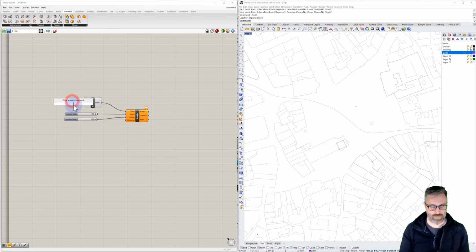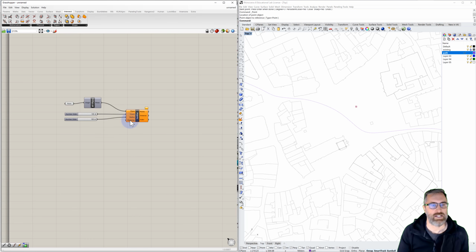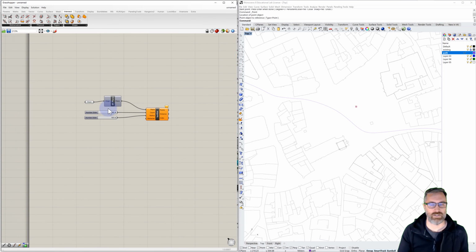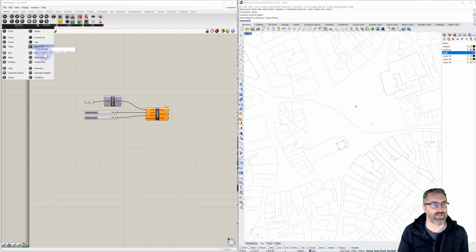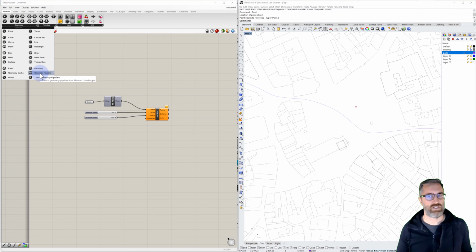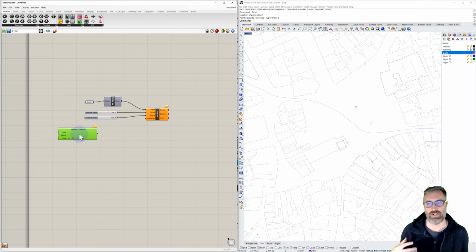And our origin, let's set a point for this. Plug in our point. We'll grab our point by setting one point, and we'll use this point in the space. Let's set the plane for us. We can hide that. And now we need obstacles. What I'm going to use for obstacles, this is a new tool. We're going to use a geometry pipeline. So under geometry, we can see Geometry Pipeline. What's really nice about this is that we just set a series of curves and lines onto a layer. And so we'll use Geometry Pipeline. And what it will do is it'll basically query something based on a layer or based on names or something else. So under layer, we can see it's just a wildcard here. Let's double click layer. And I'm going to type existing.